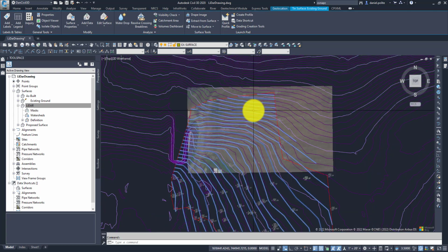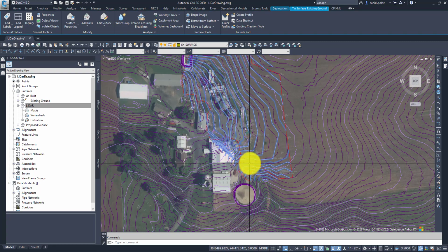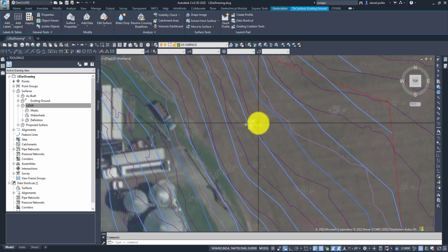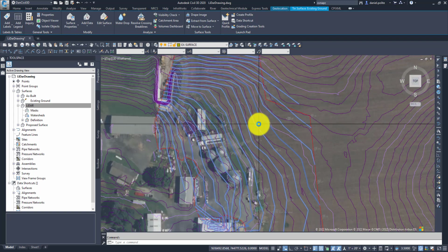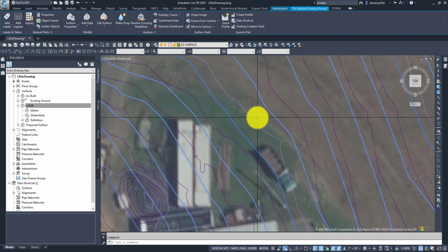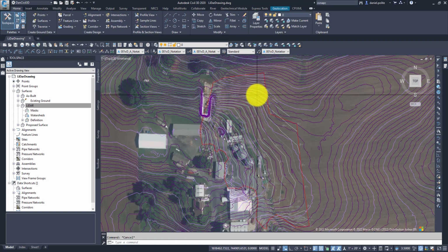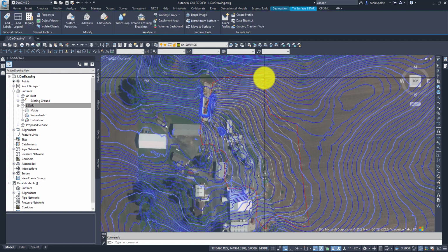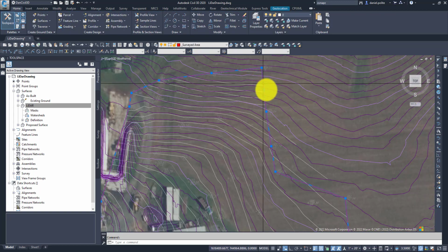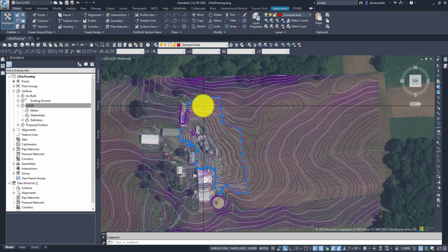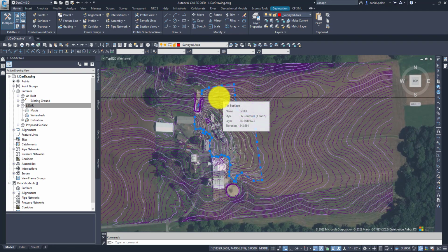And if you notice, here's my existing surface that was actually surveyed with points, locations. These were actually surveyed points. I want to keep those surveyed points. I don't want to adjust those. I want to adjust the LiDAR to match that. So we have this boundary that was created going around the outside of our survey boundary that we want to trim our LiDAR to.